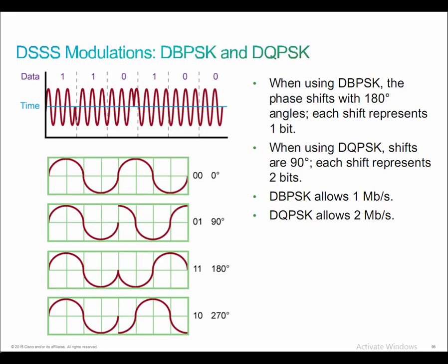Don't confuse modulation with the chipping code. Remember, we send 11 symbols in parallel, and each of those streams gets sent at a rate of 1 per microsecond, or 1 megabit per second. And because 11 symbols are being used to represent the one binary digit that we're trying to represent, if we have a 22 megahertz wide signal, that's going to contain 11 parallel symbols, resulting in 1 meg of actual real throughput data.